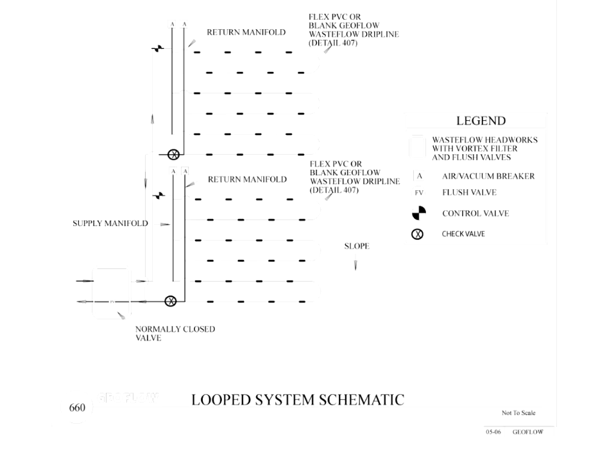Okay, and this is a fairly typical design. Here you'll have your pump tank, and you'll have a supply manifold going up there and going out into solenoid valves, which will be supplying the two fields. And you notice if this is the slope, I've brought in the supply at the top, and the flush is taken out at the bottom. So we're supplying at the top, and it's going around, and then when you open this valve, it drains out rapidly through to the bottom.